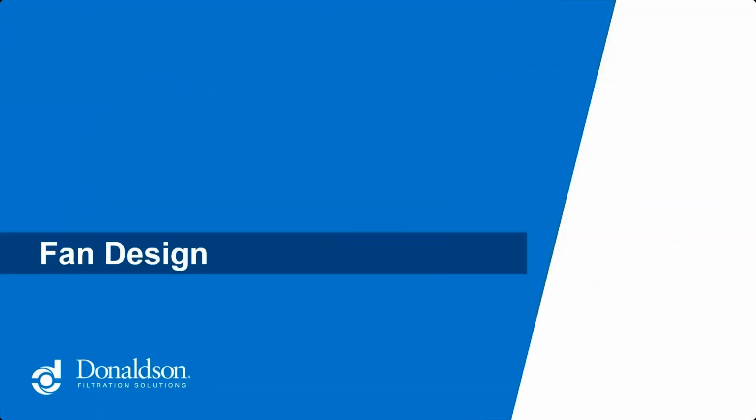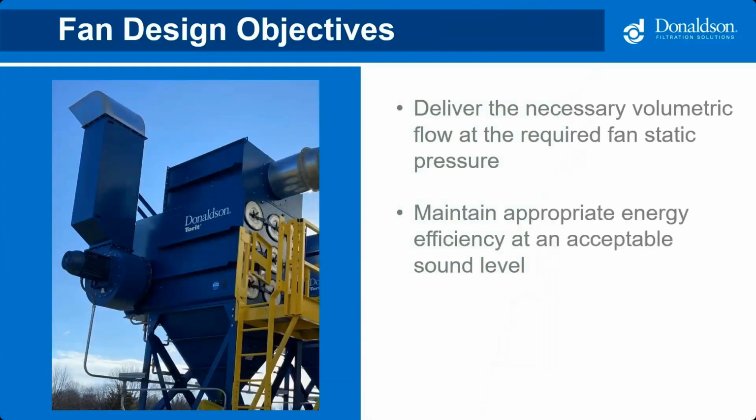All right, so moving on to the last system component, or one of the last system components, the fan. Let me explain how we size and choose a fan. So the fan has two main job responsibilities. So first, it must deliver the necessary volumetric flow at the required static pressure to drive operation of the system. And since many of the dust collectors can operate with clean or dirty filters, the required airflow must be maintained over a range of static pressures, whether the filters are clean or they're dirty.